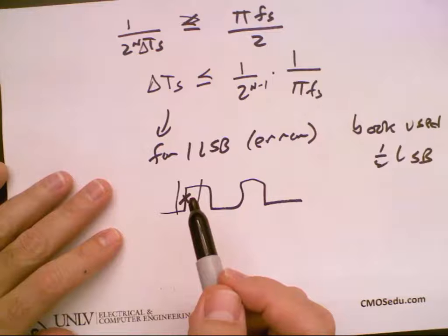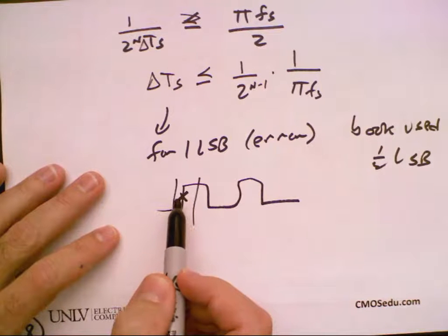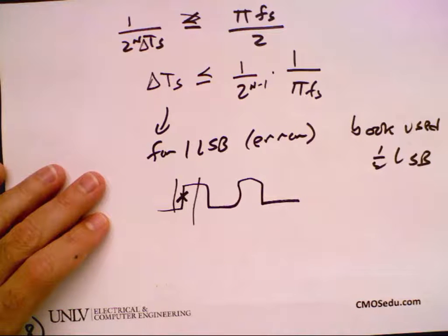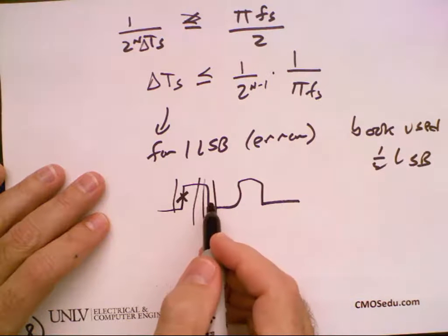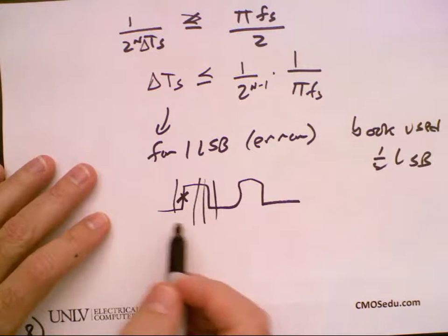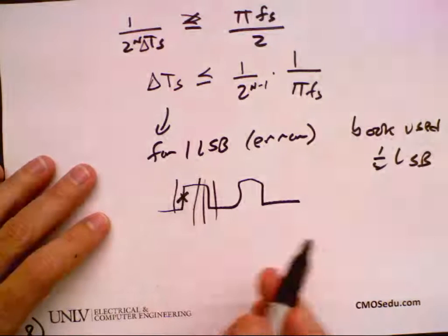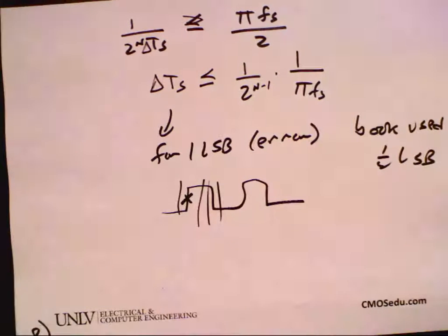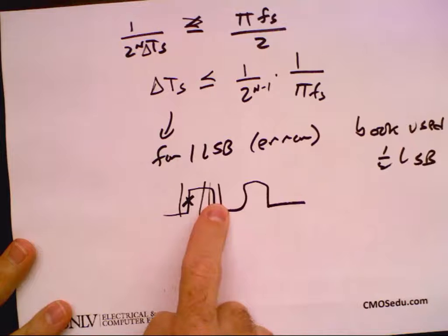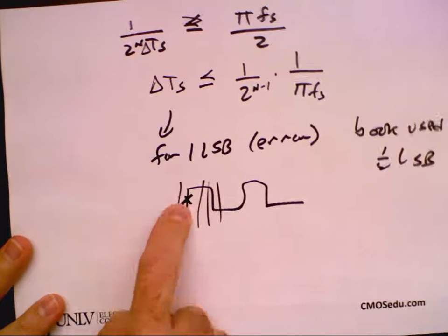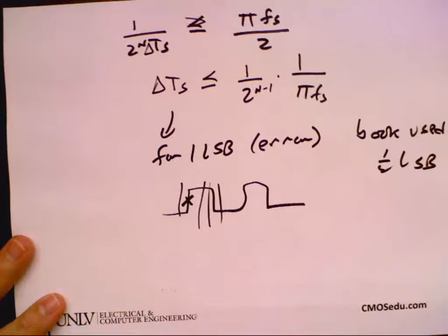It's not going to be anything, right? I'm triggering on the thing that's supposed to be moving. It could be moving all over the place, but I'm not taking a trace till I cross that point. I have to look at this edge to see the jitter, or I have to take an external trigger and lock to this somehow and look at the jitter that way. Does everybody follow that? Where I trigger says, tell me where to look, and it's telling me where to look every time. That's not changing, because I'm waiting for it to tell me. So I go to the falling edge and look at that, and it tells me how much that falling edge moves. If I look at the rising edge, then I trigger on the falling edge and go look. Does everybody follow? It's a very practical problem.